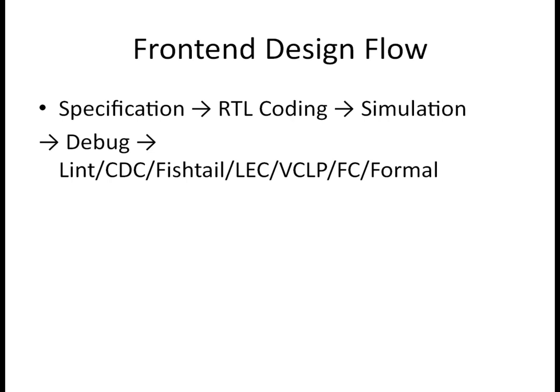For the FIFO synchronizer, we can use it if a signal is going from a fast domain to a slow domain, and the receiver side is not able to process or sample the data coming from the fast domain. In that case, we need to store the data in memory, and as per the read write pointer synchronization, we can take the data out and receive the data in the receiver domain. So this is about CDC.